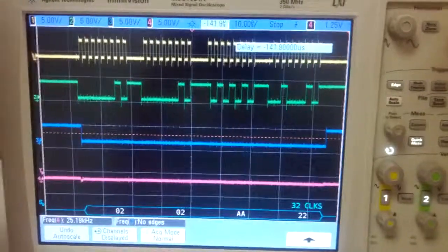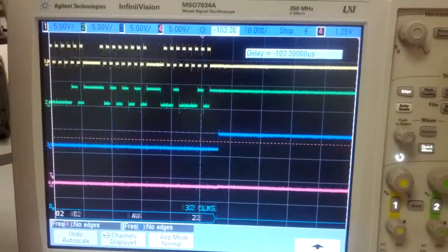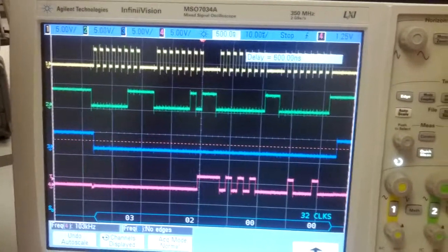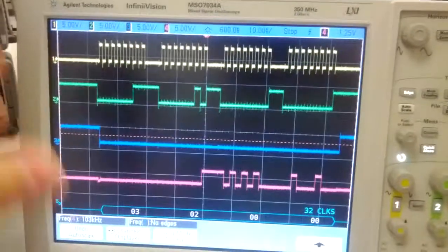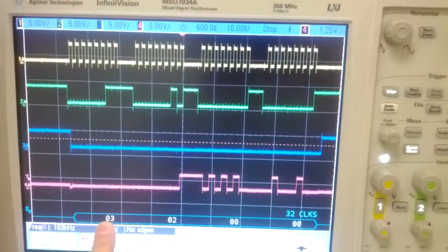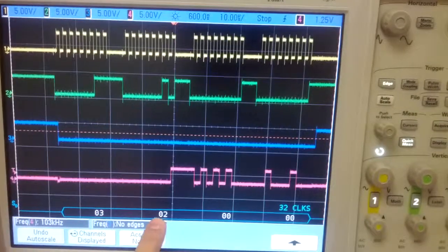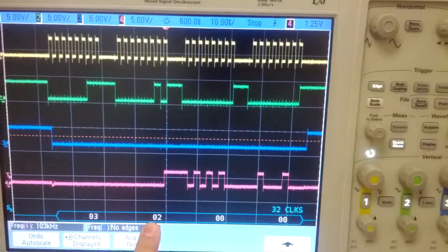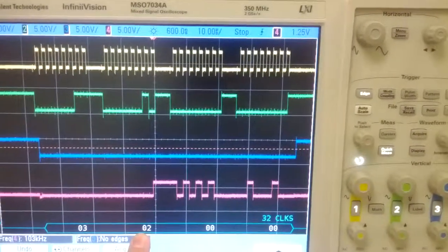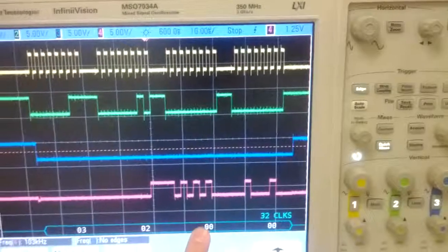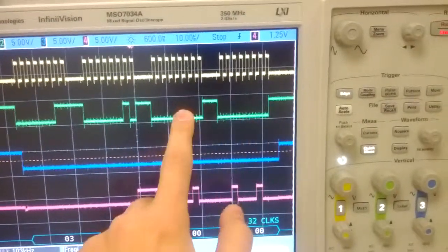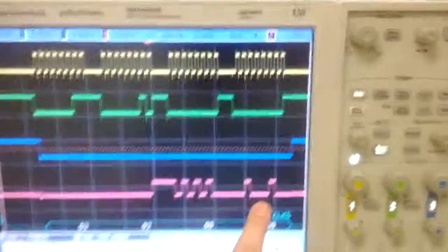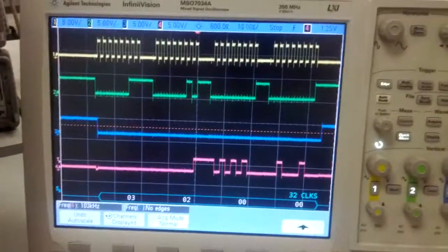And now to show that the device actually received this, I will read from the device. So reading from the device, instead of sending a 2, I send it a 3, and now it knows that I want to read. And now I tell it what register I'm interested in reading, and that is the bass control register. The AA22 I just sent doesn't have it decoded here, for it's decoding these, which are don't cares now. But as you can see here is AA and 22. So this concludes this section of my demo.